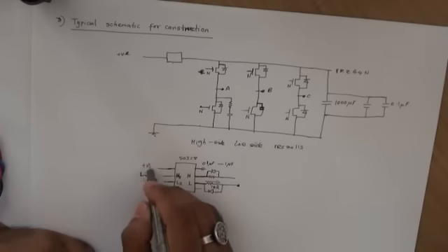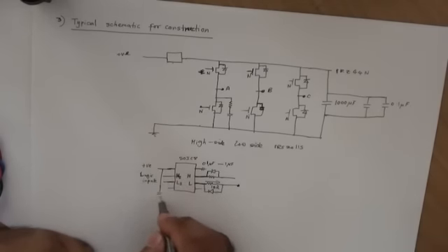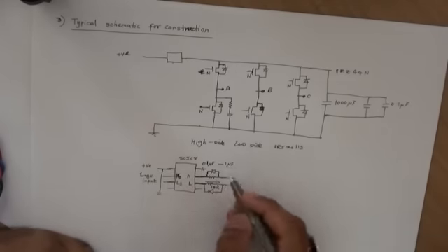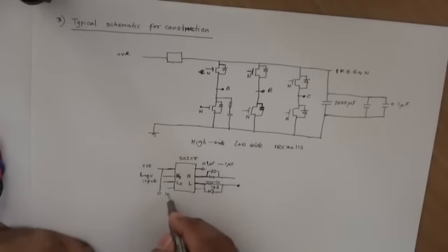So if this was your positive, then you want to have your filter capacitor 10 times. Let's say your charge pump was 1 microfarad, and then you want to have your filter cap as 10 microfarad to your ground.